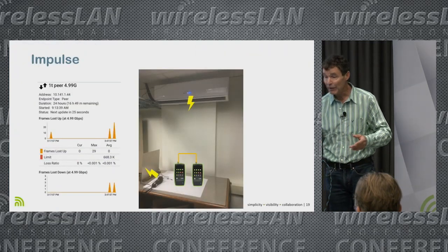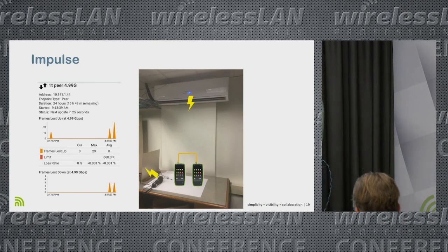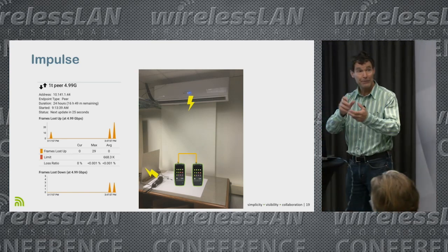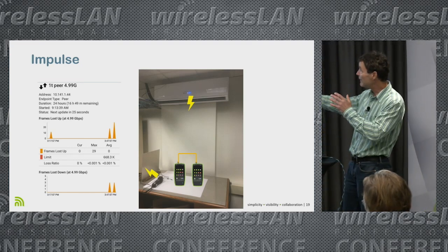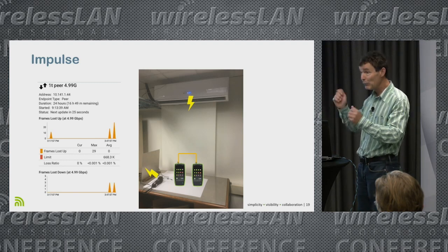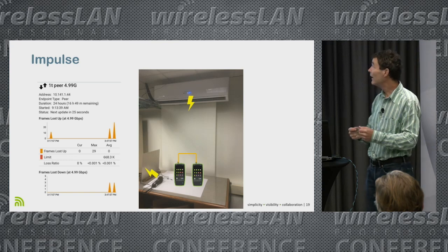Once we became aware of that, we're like, well, we can emulate this. So we go back into the lab again. This is an ESD gun here on the lower left of the picture, and we can set it up to any charge level we want and discharge it on that piece of metal. And sure enough, we'd run our line rate performance test, and every time we sparked it, we'd see frame loss on the wire.